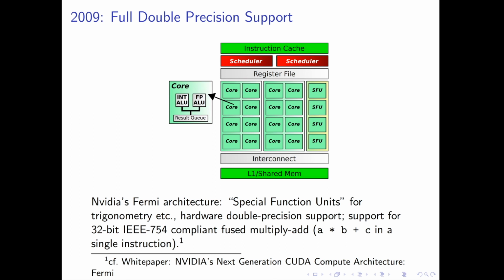And so the Fermi architecture was actually a pretty powerful architecture and made quite a jump in performance because of the scheduler that the architecture shipped with. When we run a program on this unified shader core, there needs to be some management of how threads are scheduled on those cores. And the scheduler with this architecture actually improved quite a bit. And therefore, the Fermi architecture actually made quite a jump in performance with respect to the previous generation of GPUs.